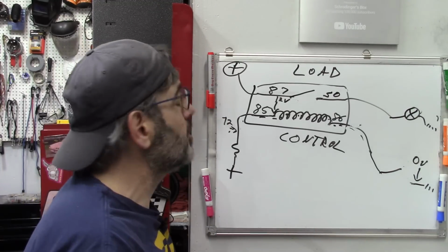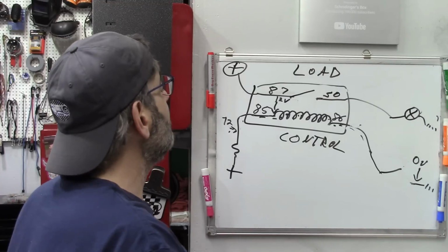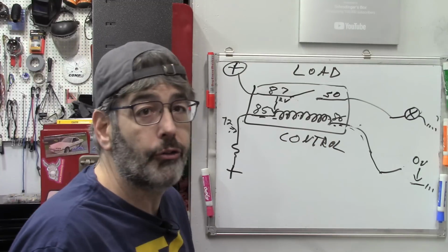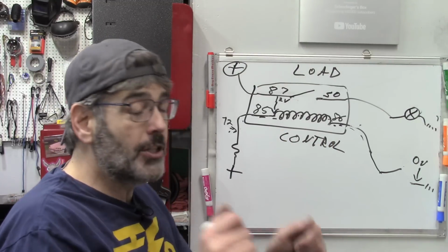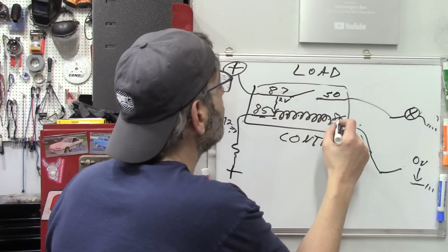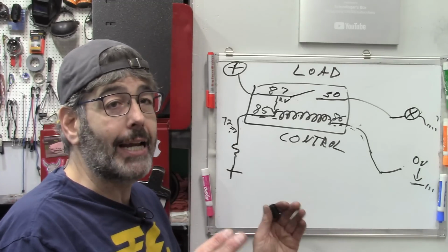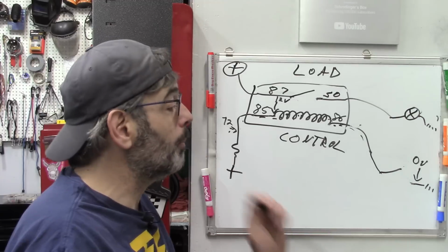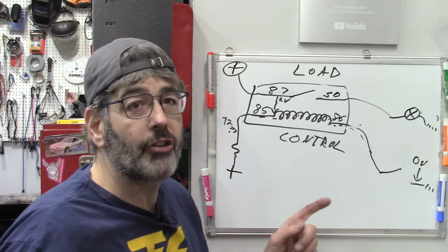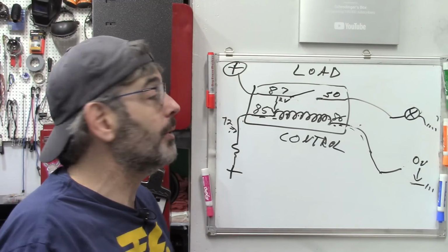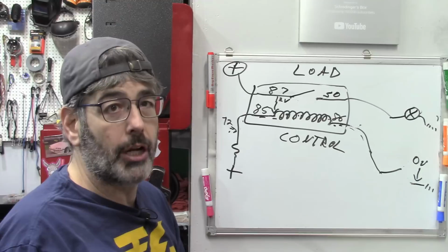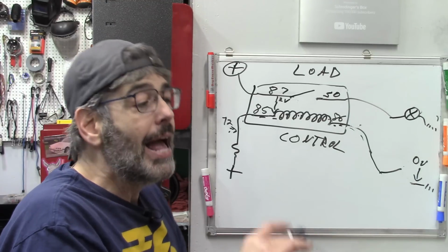It's going to be very easy to find the control side on a relay, even just with the relay itself, because we're going to have continuity on that coil side. We will be able to see that with the meter, as opposed to the load side of the relay where there won't be continuity. So by using our DVOM in a continuity mode, we will be able to tell the load side and the control side.